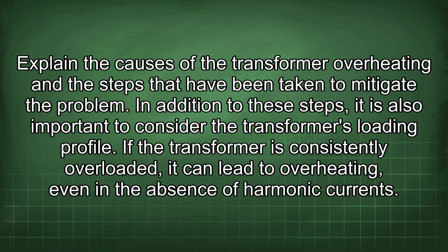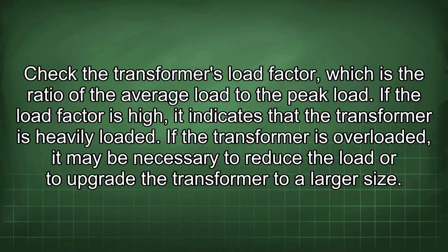In addition to these steps, it is also important to consider the transformer's loading profile. If the transformer is consistently overloaded, it can lead to overheating even in the absence of harmonic currents. Check the transformer's load factor, which is the ratio of the average load to the peak load. If the load factor is high, it indicates that the transformer is heavily loaded. If the transformer is overloaded, it may be necessary to reduce the load or to upgrade the transformer to a larger size.